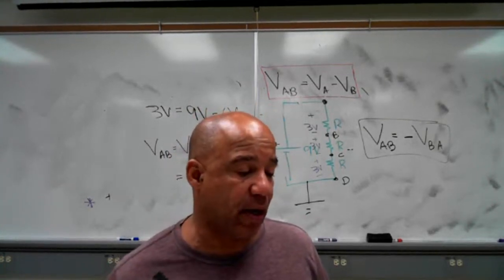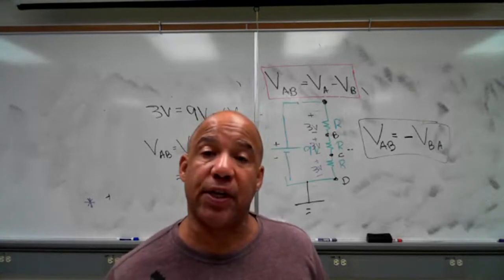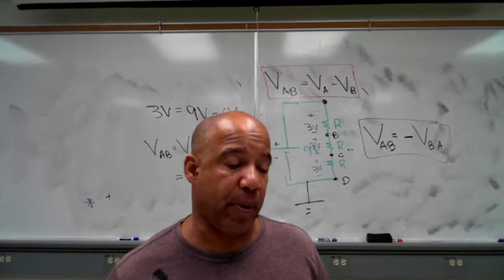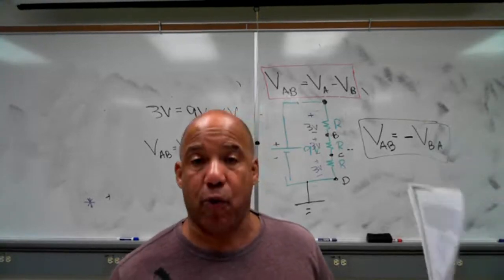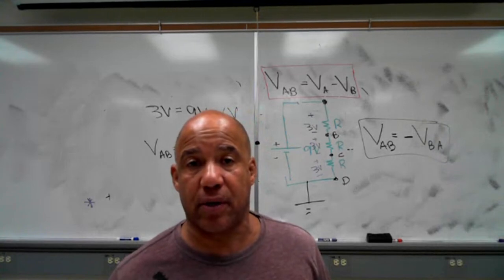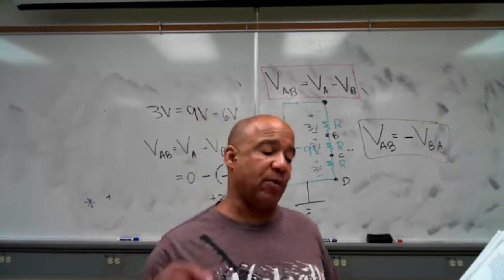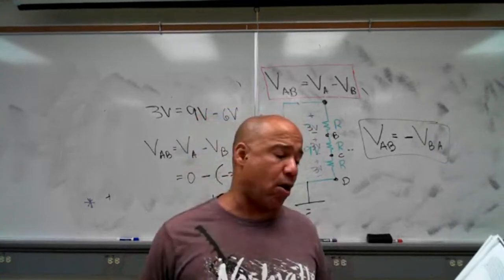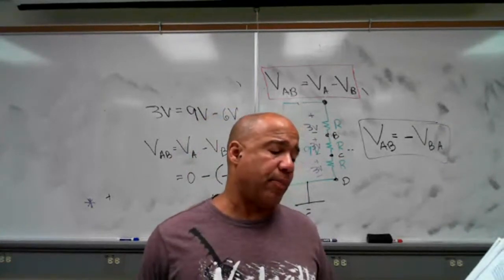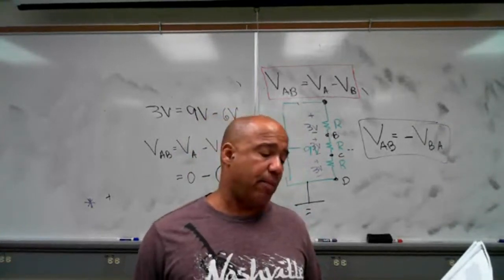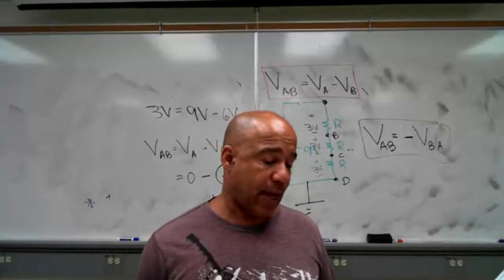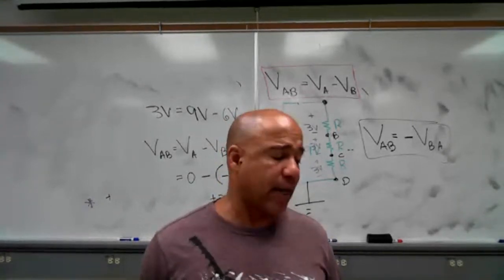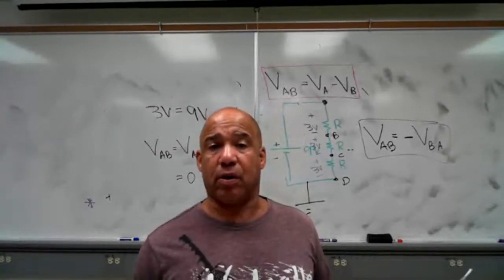It's just a series circuit with 3 resistors, but notice the points A, B, C, and D. It's important that you know where those points are in your circuit. And the other thing, you want to have the resistors in the order shown. So make R1 the 330, make R2 the 680, make R3 the 10K, or is that 1K? 1K. So put them in that order.